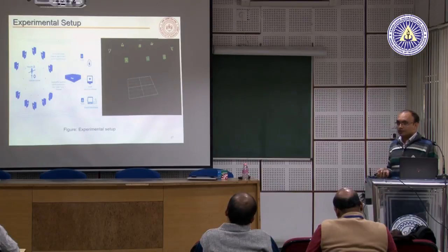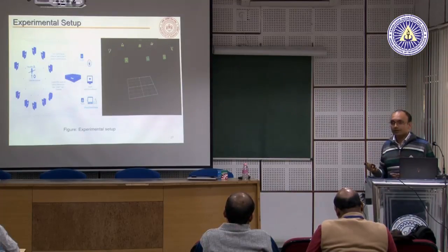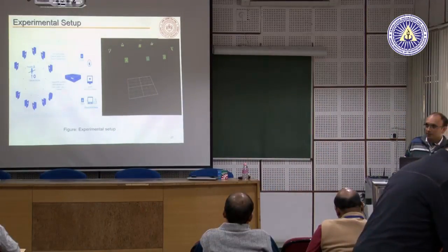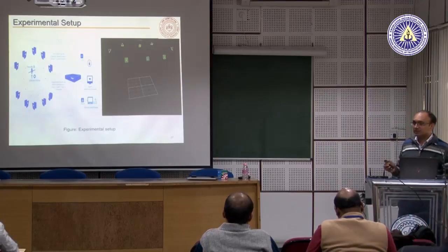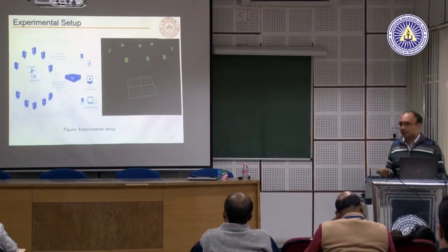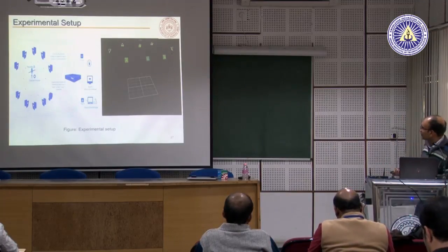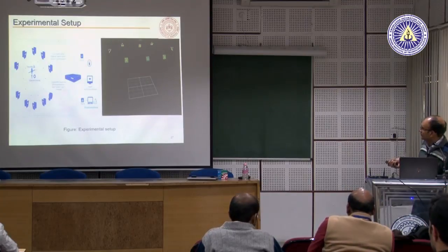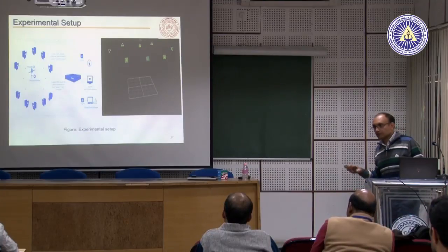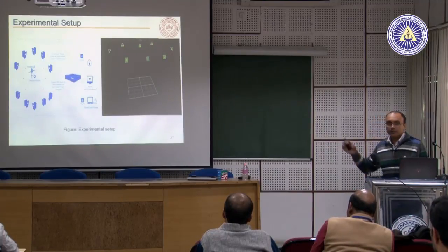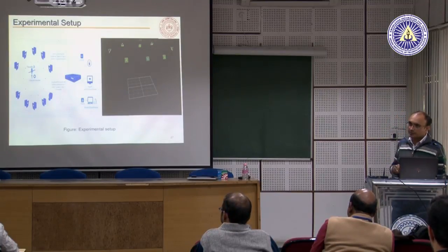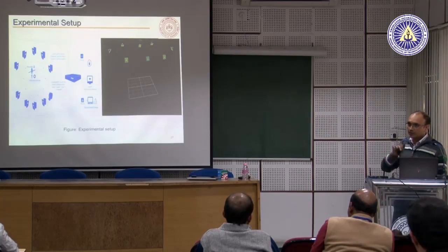The key challenge with all helicopters and flight vehicles is normally localization, which is a big topic in electrical engineering also, especially in GPS denied environments. When GPS is not working, how do you localize your vehicle and its location? To get that in the indoor environment, there is a company called Vicon. There are now other companies also which manufacture this camera system. You will have multiple cameras installed on the roof of your room, and these are IR cameras. They throw some kind of IR beam and they look at only IR.